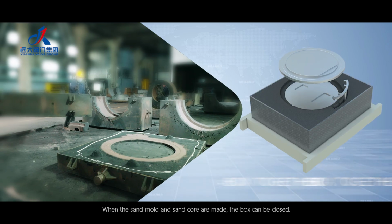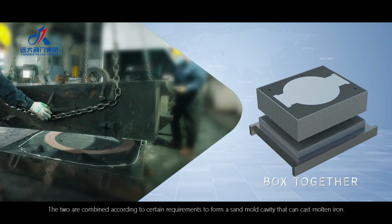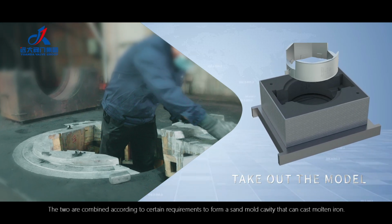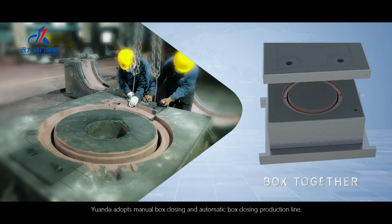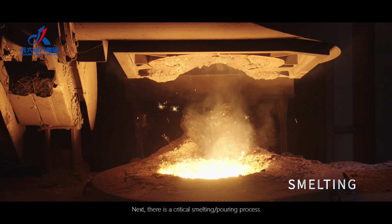When the sand mold and sand core are made, the box can be closed. The two are combined according to certain requirements to form a sand mold cavity that can cast molten iron. Waiting for the subsequent molten iron pouring, Yuanda adopts manual box closing and automatic box closing production line. Next, there is a critical smelting/pouring process.